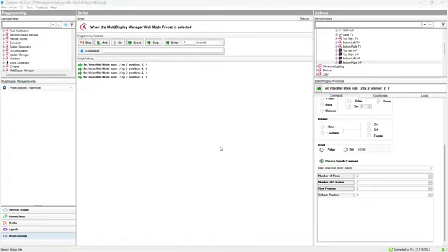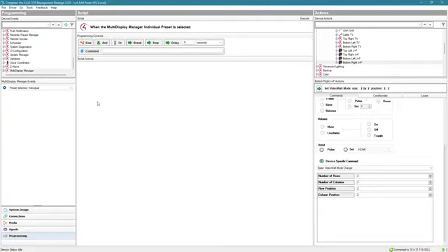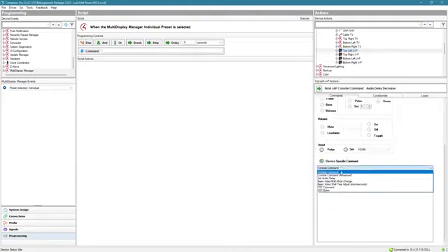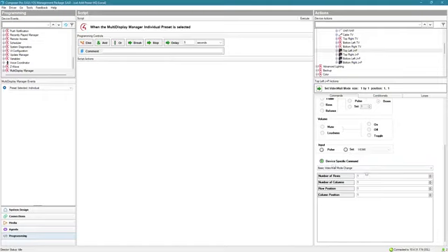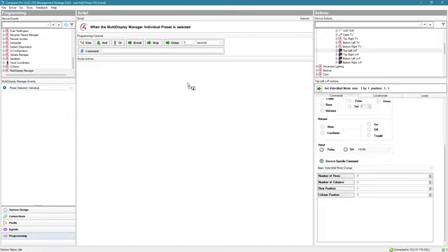And now we have to build the macro to go the other way, because right now it's in wall mode, but it's kind of stuck in wall mode. If I hit individuals, nothing happens. Even if it switches to different sources, I've got the corner of 4 different sources. So when we do an individual mode, we have to tell the Just Add Power receivers to be a single television. So again, we go down to basic video wall mode change, but this time we leave all the numbers at 1. Rows, columns, position, column position, all at 1, because they are just all by their lonesomes.